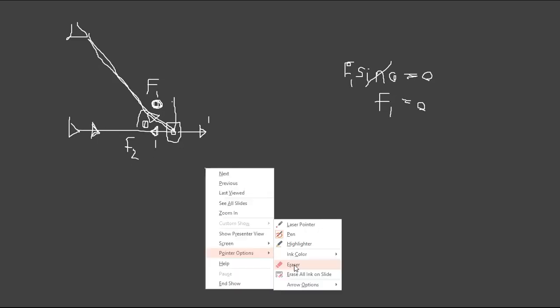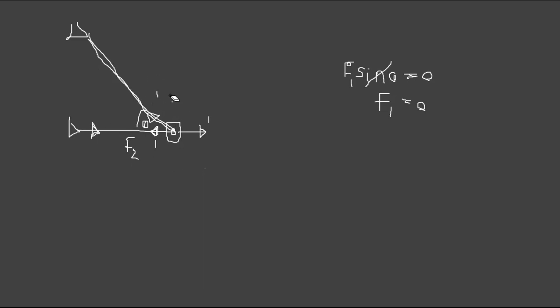So F2, let's say theta, F1 into sine theta is equal to 0, no other load. So sine theta is not 0, so F1 is 0, right? So this load is entirely taken by this member and it's a tension, right? This is 45, okay.